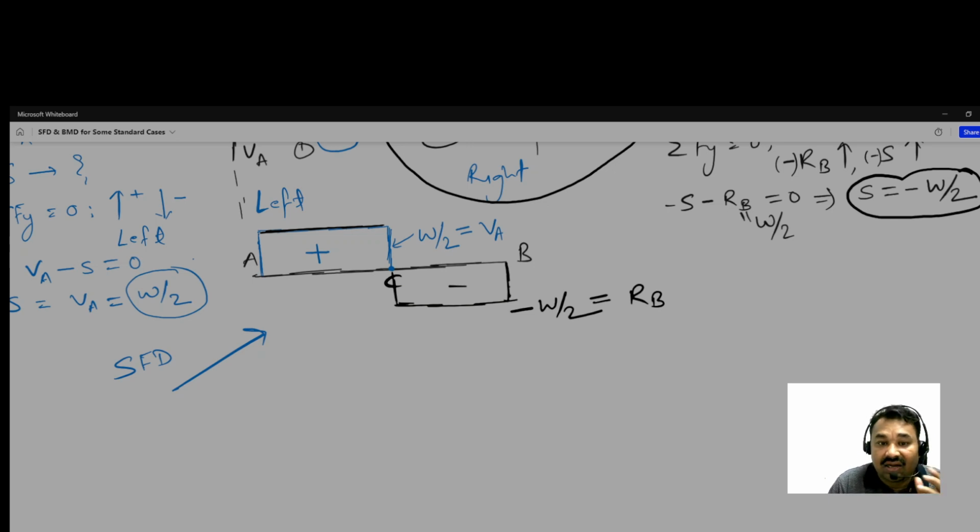What about the bending moment? However, it is very obvious from observation. By seeing these, we can get how it varies, like A, this is B, and it is C. So how it varies from A to C. And the bending moment at the supports is the resisting moment. So at the ends, you can understand it this way: where there are supports, the chance of failure is low. So at A there is a support and at B there is a support, so the bending moment diagram will be 0. And where there is load, there will be a chance of deformation. So at A and B it is obviously 0. It starts from 0.